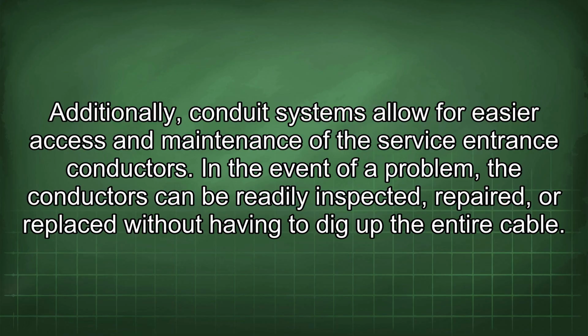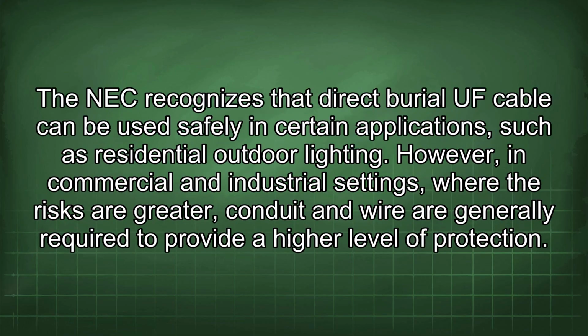The NEC recognizes that direct burial UF cable can be used safely in certain applications such as residential outdoor lighting. However, in commercial and industrial settings, where the risks are greater, conduit and wire are generally required to provide a higher level of protection.